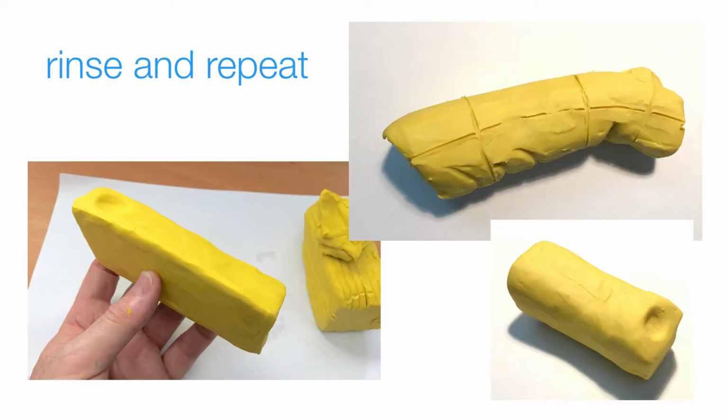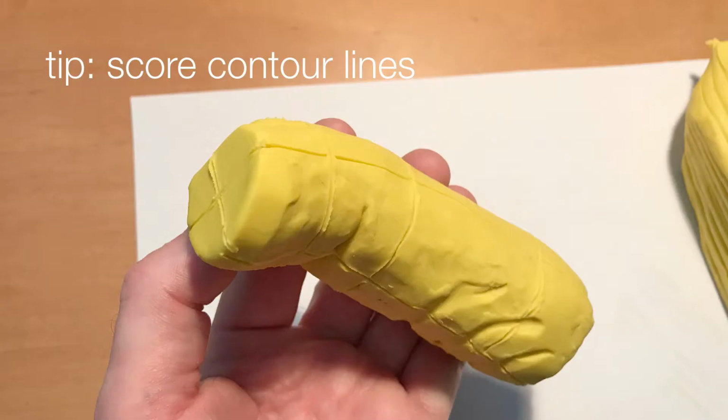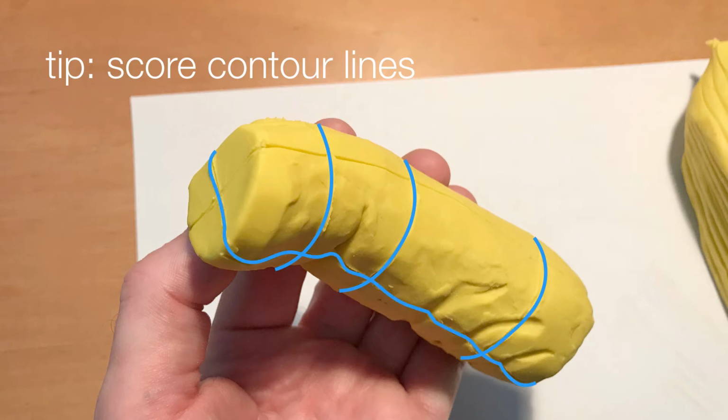So you want to try this in an iterative process, to rinse and repeat. And this iteration is a fundamental part of the industrial design process. So we don't just stop at our first idea. We keep learning from it and improving and thinking of quite different ideas through analysis and idea generation. Now, here's a tip: when you work in plasticine or even in foam, you can score or draw lines onto the model before you photograph it. And these lines can make it a little bit easier when you do the analysis a little bit later on, because you can just draw over these contours.